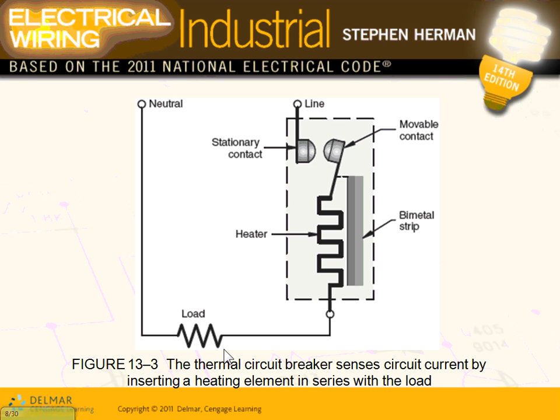Take this. If this is my load, guys, and I have a circuit breaker, this circuit breaker is at 20 amp, right? Now, if I pull out of this system 30 amp, this is rated 20 amp thermal circuit breaker, and I'm pulling 30 amp. I'm overloading it. So this 30 amp is going to go through where? Through all this heater. The heater is rated not to trip up to 20 amp. You put higher than 20 amp, it starts heating more, creating more heat, more heat. And guess what? After a while, this will expand, push this way, and it will open the contacts, right?